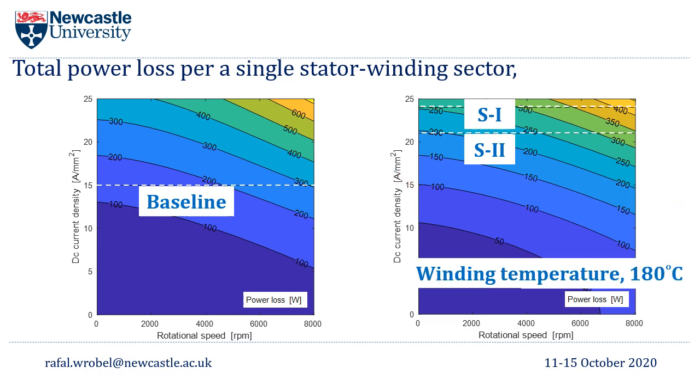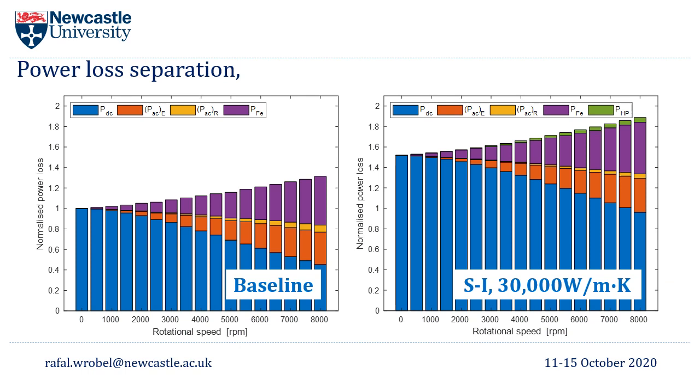Looking at the individual loss components in more detail, we've generated two or three additional figures where we have a normalized power loss versus rotational speed. Again, just a simple maximum torque per amp operation is analyzed here with all loss components, including DC winding, AC excitation, AC rotational winding, and then iron losses. In the case of the heat pipe system, also heat pipe loss components.